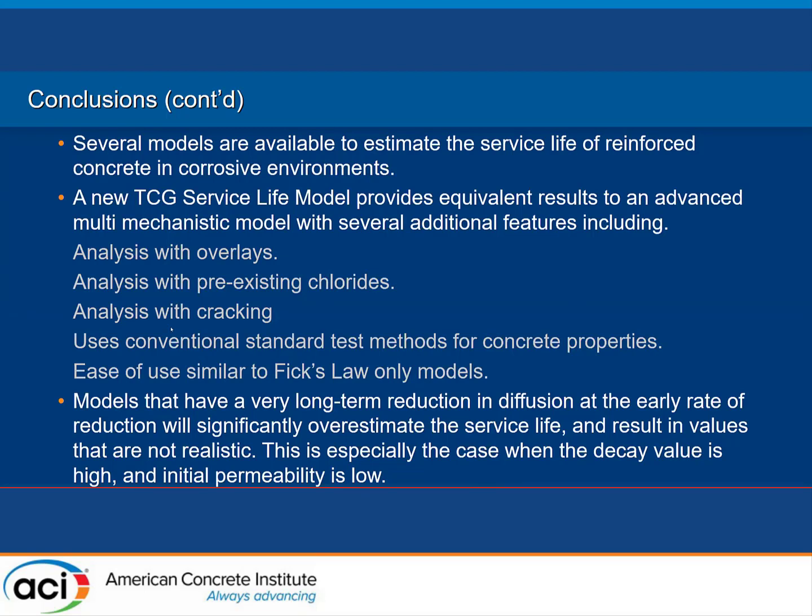You can look at cracking using conventional standard test methods for concrete properties, easy to use. I just give a warning that models with long-term reduction in diffusion, especially if they have a lot of SCMs in them, could overestimate the amount of time that the concrete is going to last. And I'll leave it at that.